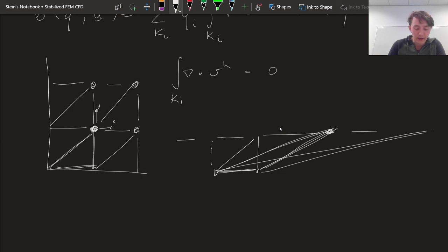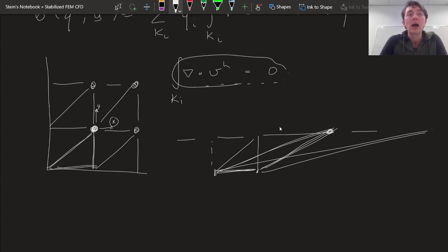So my x degree of freedom is still free. Any choice of Vx is going to satisfy this requirement, but the y direction does not, right? So I'm actually completely constrained in Vy, in the sense that for this particular element we can already conclude that Vy has to be equal to 0. Again, for this element, on this node. Right? Vy is equal to 0, and Vx is still free.